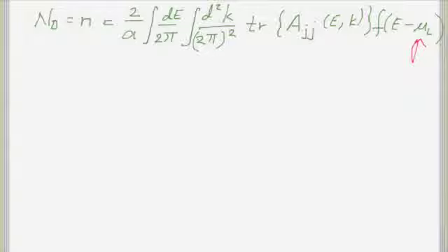Once you have mu, then you know where your conduction band is here, and then you set this. If you're doing a full band calculation, your band edge is going to occur at some strange energy like -5 eV or something, depending on whatever your full band parameters are. And they can vary however people set them up, or it could be +2 eV.